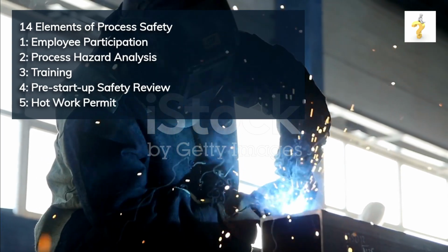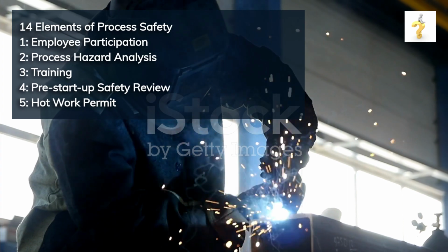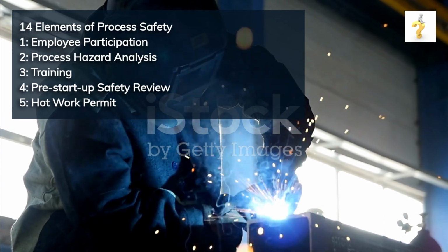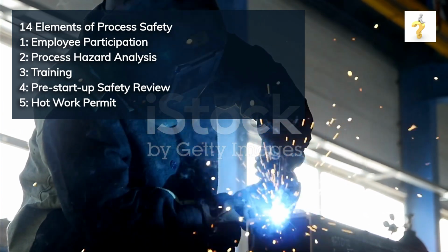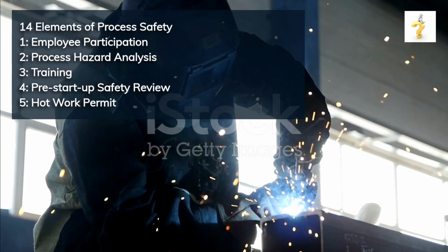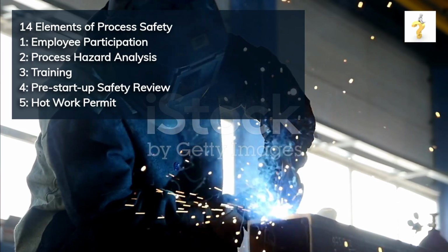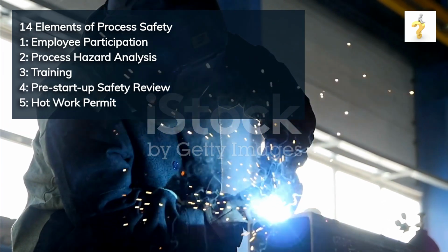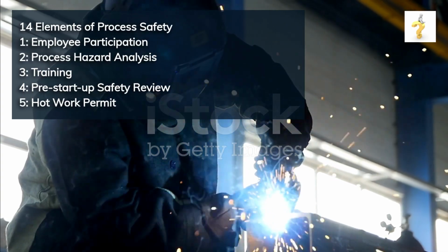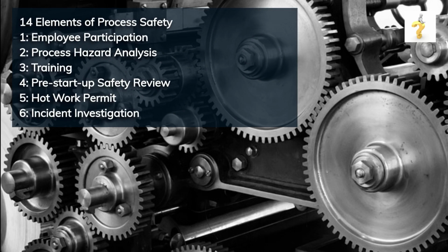The hot work permit process typically involves assessing the work area, identifying potential fire hazards, ensuring the availability of fire prevention and suppression equipment, and obtaining authorization from authorized personnel. By implementing a hot work permit system, organizations can prevent fire incidents and protect the safety of workers and the surrounding environment. Incident investigation is the sixth element of PSM.